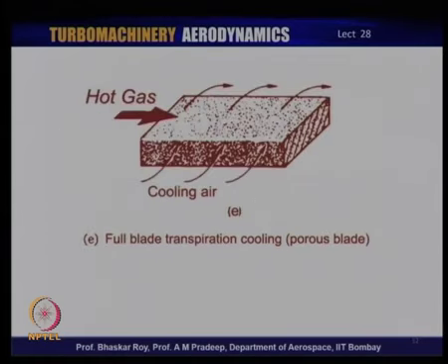Now, the transpiration cooling, which people have been talking about for 50 years now, actually involves a porous solid body or outer shell of the turbine blade. So, you have cold air oozing out like perspiration through this solid body of the blades to create continuous film cooling. Now, this is of course the ultimate ideal of film cooling. You just allow the air to go inside the turbine blades, the internal passage of the blades, with some pressure, and that pressure will drive the flow out through these pores. So, it is a porous body, and through it the air will just ooze out.